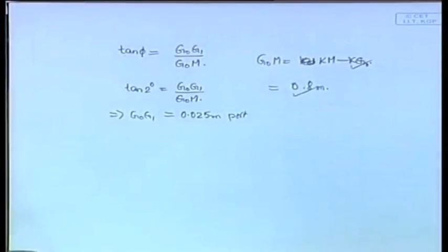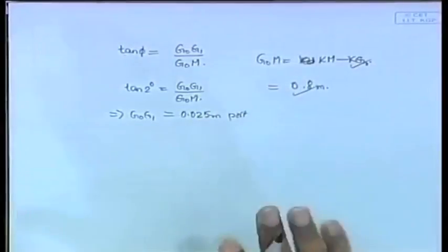That means the value of G initially is at a distance of so much meter to the port side. It is not on the center line, so actually it is heeled like this, not like this. G is somewhere here, a little distance away from the center line. Okay. This is your initial condition.